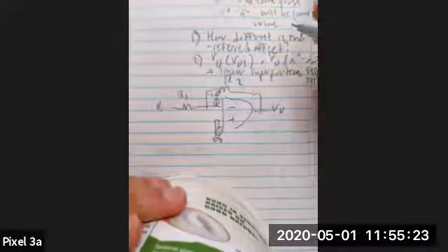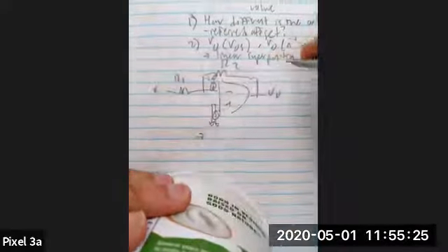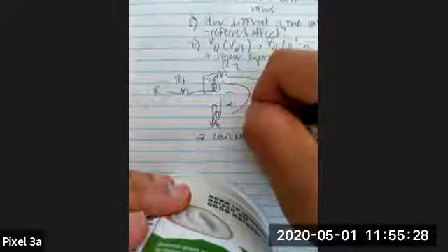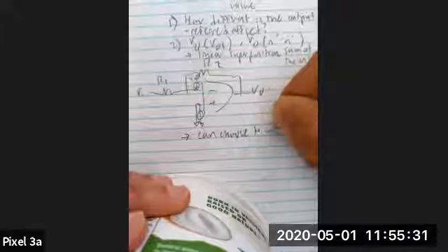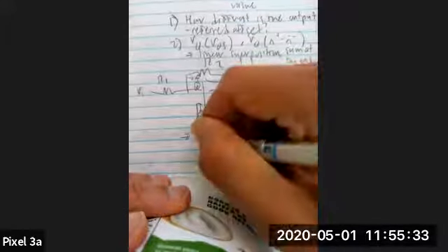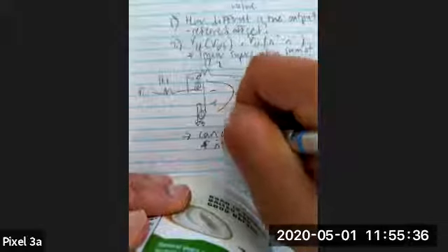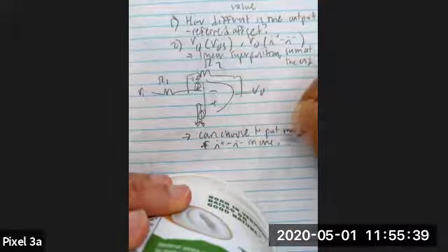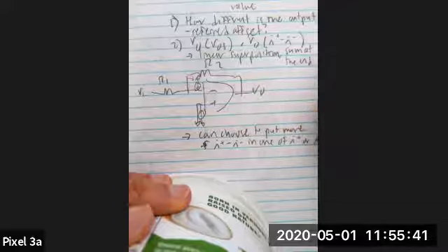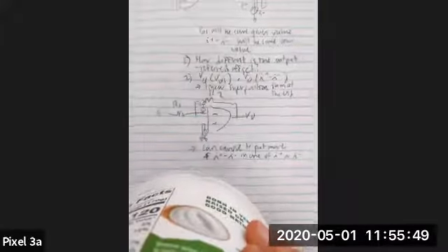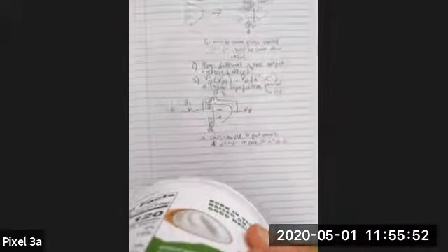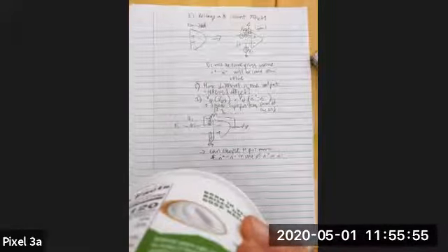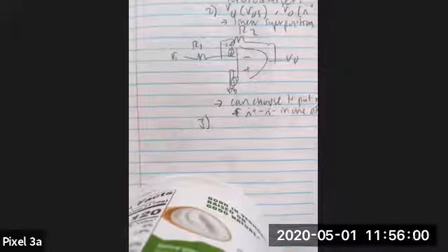So the second trick that I was going to write here is that you can choose to put more of I plus minus I minus in one of I plus or I minus, just to find the worst case. So yeah, that's covered in the homework, and I think you can probably do that. In any case, we have 5 minutes left, so I have to do the last few. And the last concept, I think, is going to be slew rate, if I'm not mistaken.